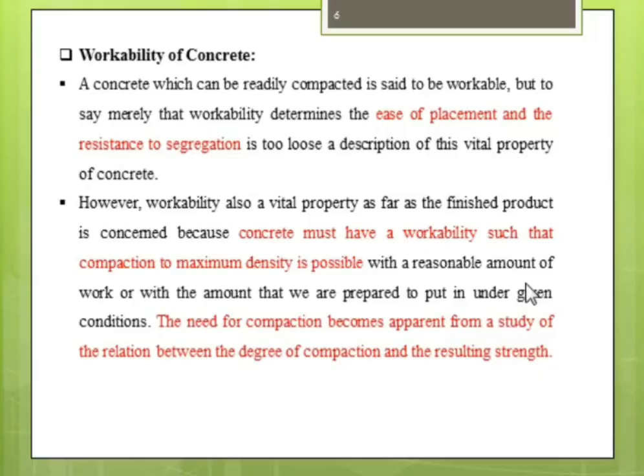So in such a case you will not get workability, meaning there is zero workability. If you test the slump cone in lower water cement ratio concrete, you will observe the slump cone as it is after removing. Okay, so that is not what we want, because for high rise buildings pumpable concrete is required with high strength. So in such cases workability is very important.